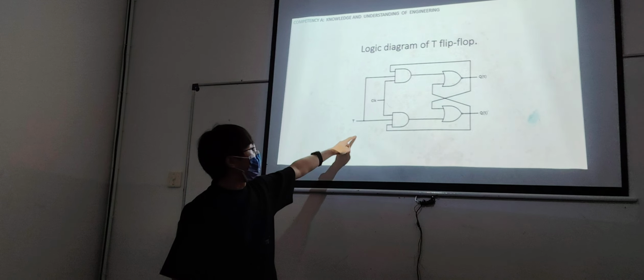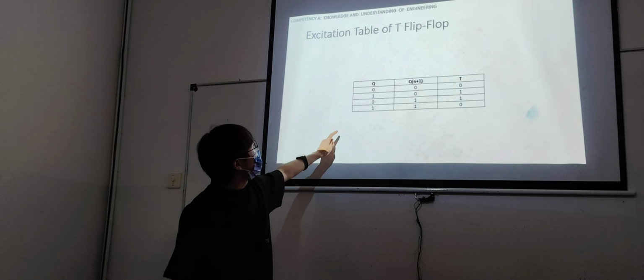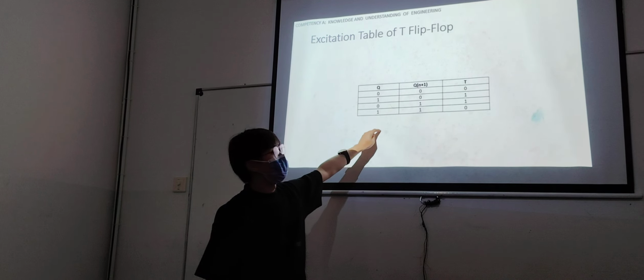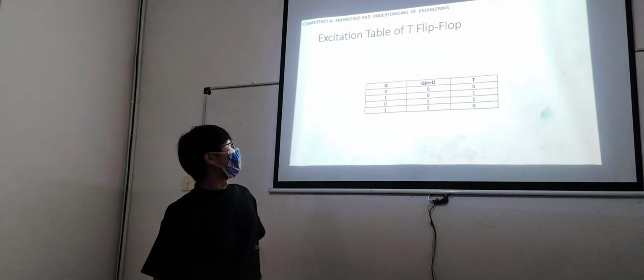Now this is a logic diagram for each flip-flop, and this is an excitation table of the flip-flop. And we designed the circuit based on this excitation table that we obtained from the next-state table.